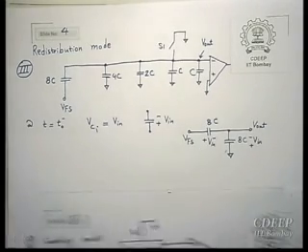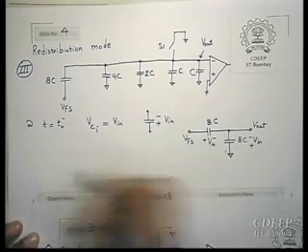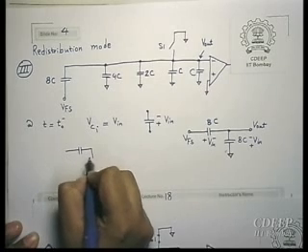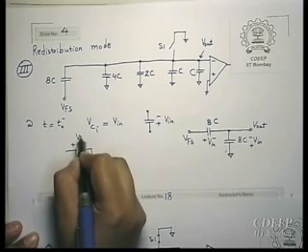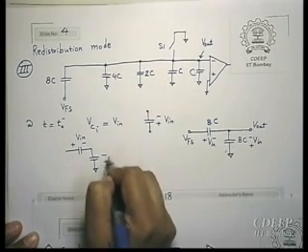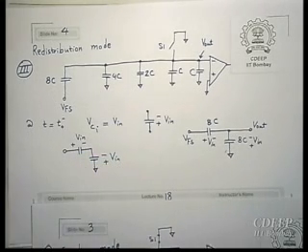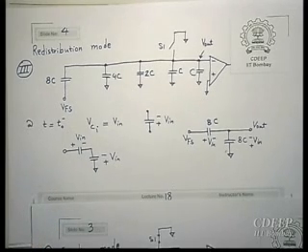So therefore, you can consider it as this. If you look at this situation, the summation of voltages across these capacitors is 0. Okay? Therefore, either you keep it this way or you connect it to ground, nothing changes. Now you are increasing this node by the amount of V full scale. Suppose it was ground, assume it is ground.